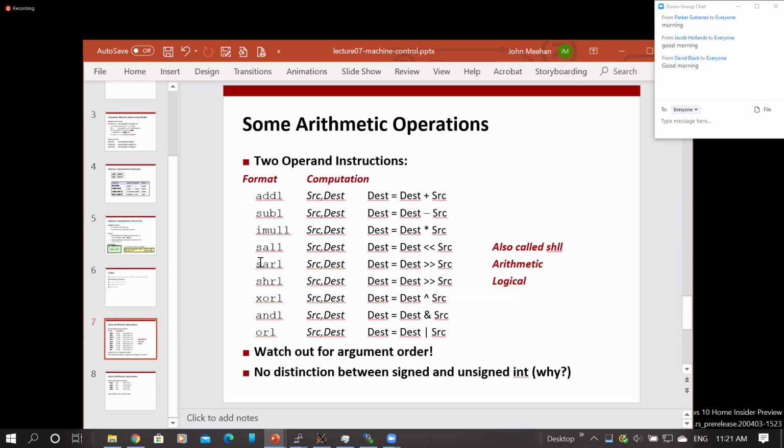And so why would we do an arithmetic shift? Well, that would be like if we had an integer, a signed type. We want to propagate that sign bit, right? The shift right is the logical shift. It's not a shift arithmetic, and that would have zeros pumped in on the left side when you're moving things to the right and vacating those positions.